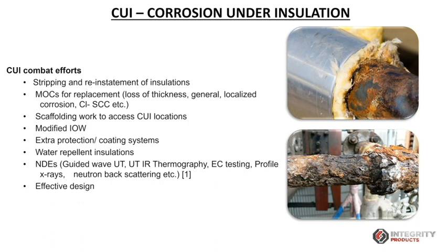Recently there has also been an advent of technology with hydrophobic insulations, the water repellent technologies that are in place. We also conduct non-destructive examination, the latest one being MDI, moisture detection imaging, infrared thermography, and we even go with general visual inspection by stripping off insulation. And the last thing is effective design. It's a huge area, and I would say a gray area, because it's the most decisive one regarding CUI; the future of CUI in our assets depends on the design. So all these are the efforts made towards CUI to minimize the probability or the consequence of CUI.